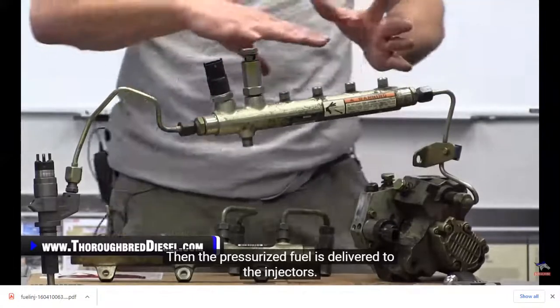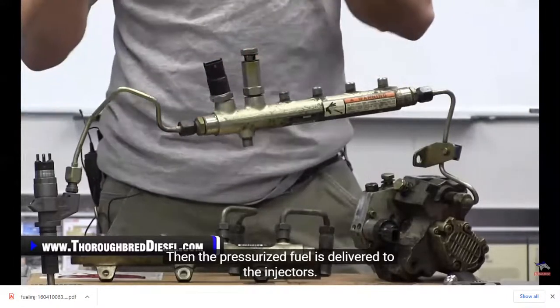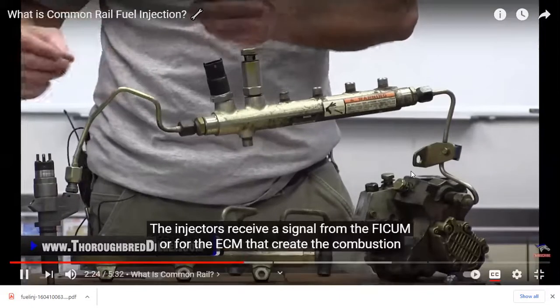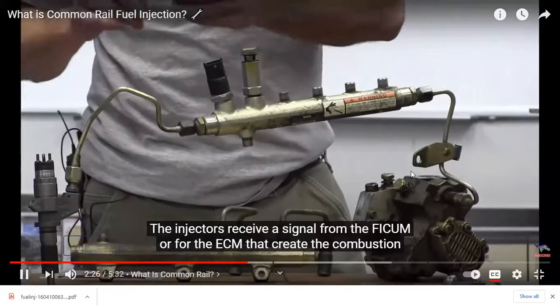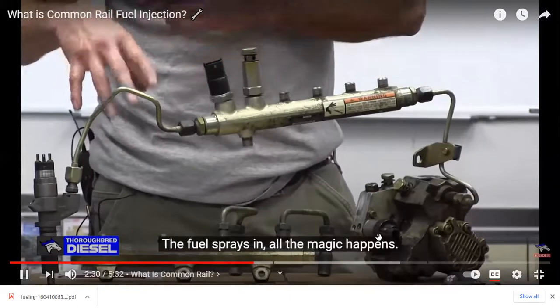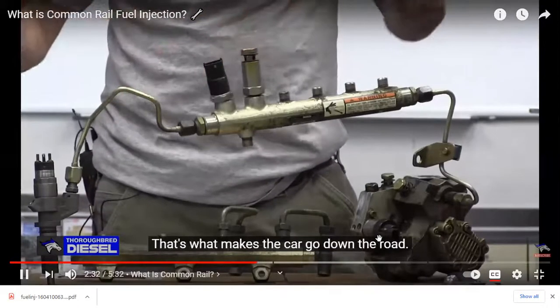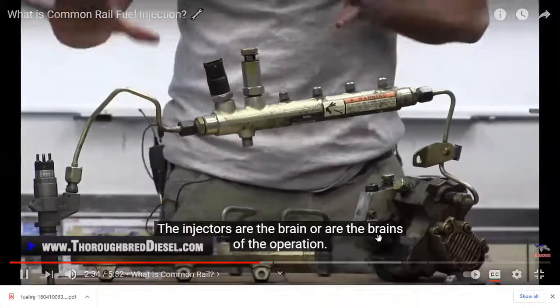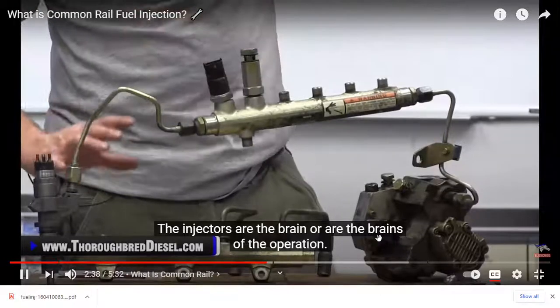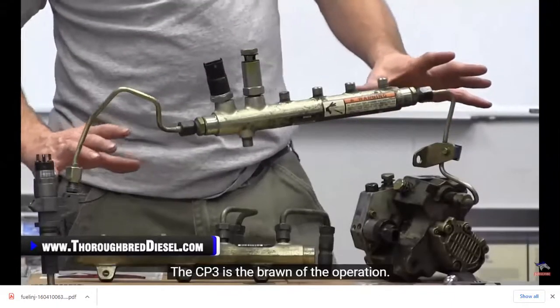Then the pressurized fuel is delivered to the injectors. The injectors receive a signal from the FICM or the ECM that creates the combustion event that goes into the cylinders. The fuel sprays in, all the magic happens. That's what makes the car go down the road. The injectors are the brain of the operation. The CP3 is the brawn of the operation.